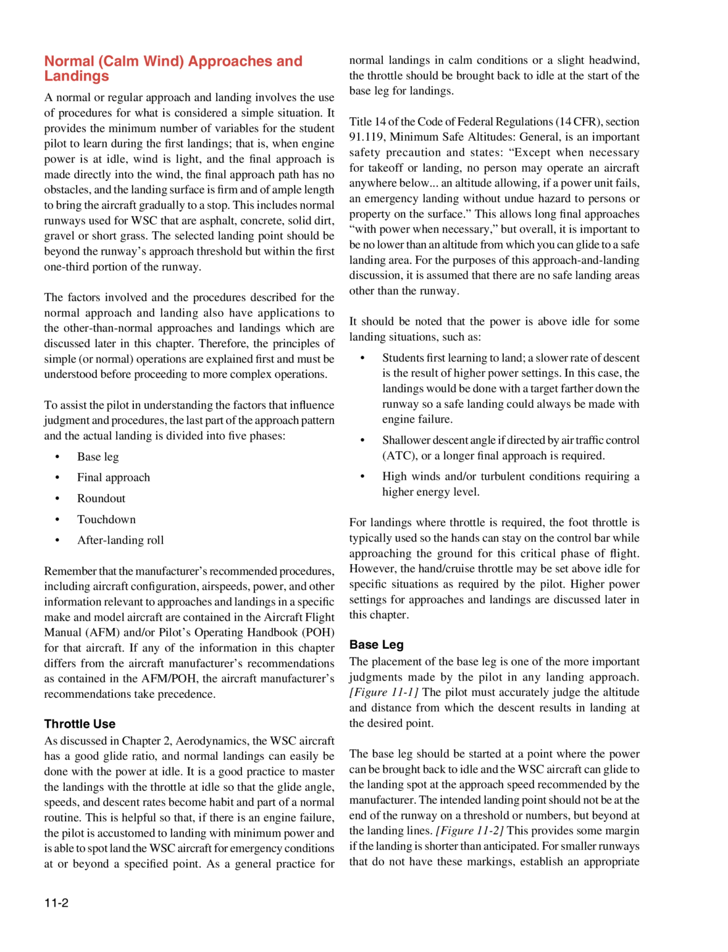Therefore, the principles of simple, or normal, operations are explained and must be understood before proceeding to more complex operations. To assist the pilot in understanding the factors that influence judgment and procedures, the last part of the approach pattern and the actual landing is divided into phases. Base leg, final approach, roundout, touchdown, and after-landing roll.